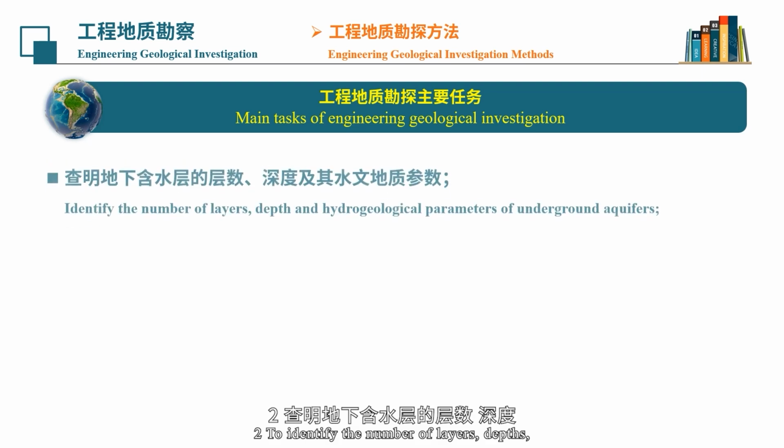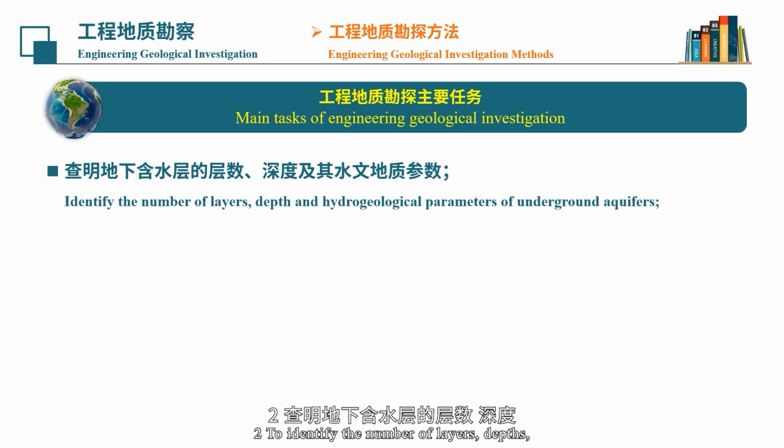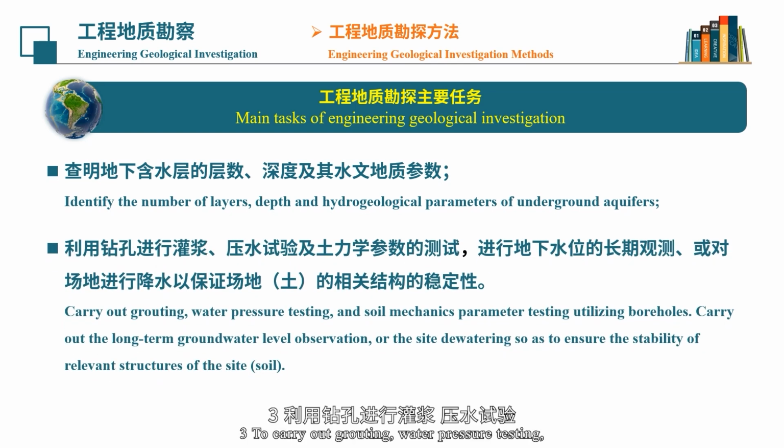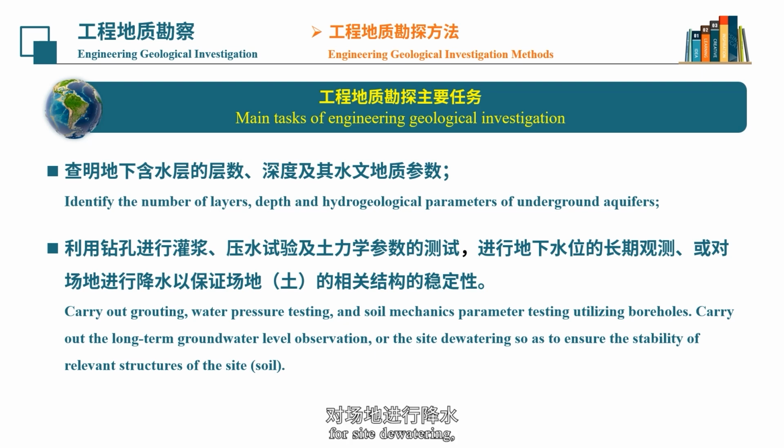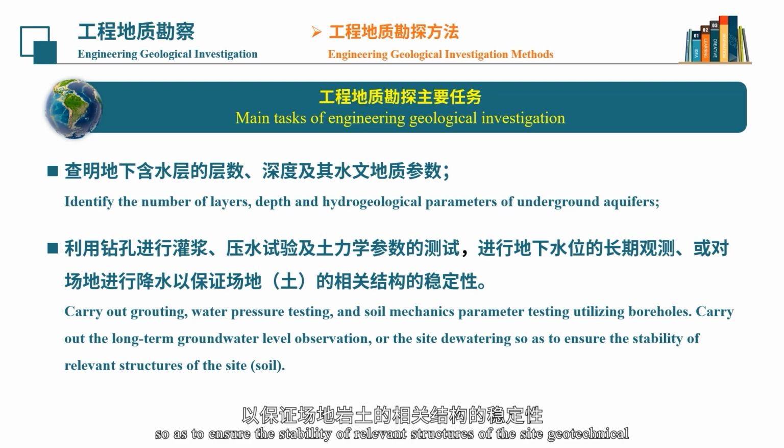2. To identify the number of layers, depths, and hydrogeological parameters of underground aquifers. 3. To carry out grouting, water pressure testing, and soil mechanics parameter testing utilizing boreholes. 4. To carry out long-term groundwater level monitoring using boreholes for site dewatering, so as to ensure the stability of relevant structures of the site geotechnical web.